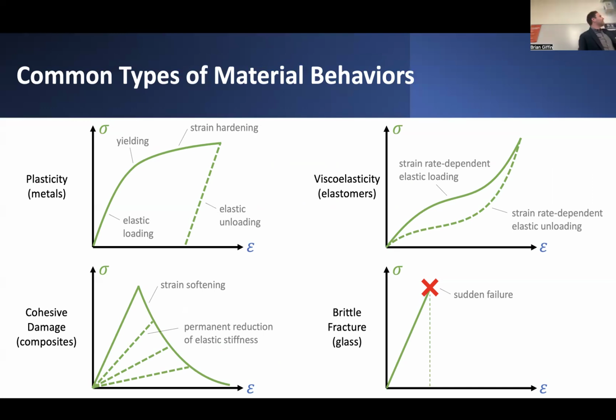And in this range where the material is actively yielding, as it's sometimes called, you'll still see maybe some residual increase in stress under increases in strain. And that range of still increasing stress is sometimes called strain hardening behavior. Now, eventually, if we unload the material, we'll unload along some elastic slope. So that's really what's characteristic of plastic behavior, elastoplastic deformations.